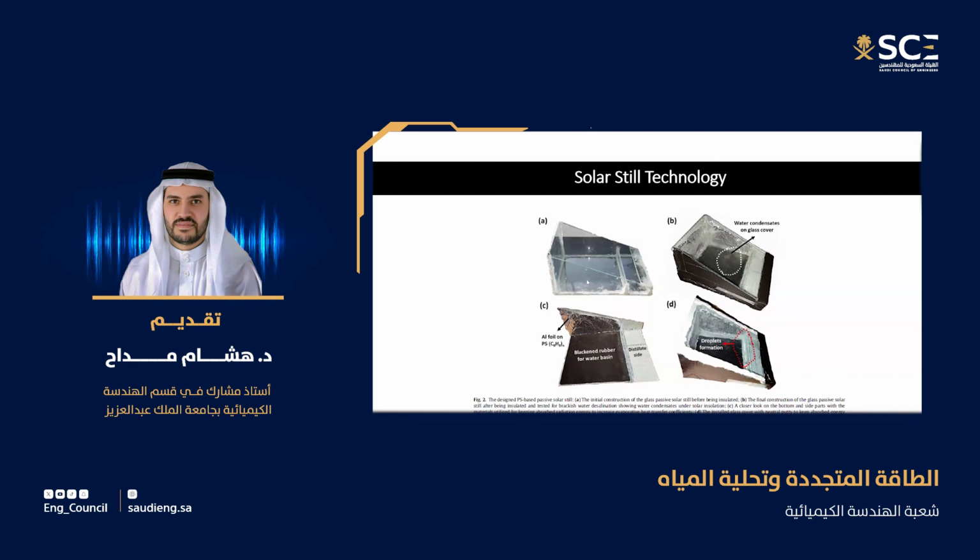You get your feed water, let's say it's seawater, and put it inside. You can also keep the system insulated. Make the system completely insulated and closed. Some people add nanoparticles to increase the efficiency of the evaporation. Some people add black rubber on the bottom of the basin, like what you have done here. You can also add polystyrene material on the walls. These all increase the insulation and keep the solar radiation inside your system as much as possible. Then you have increased evaporation and condensation, and the drops form on your inclined cover here. This is an inclined, transparent cover.